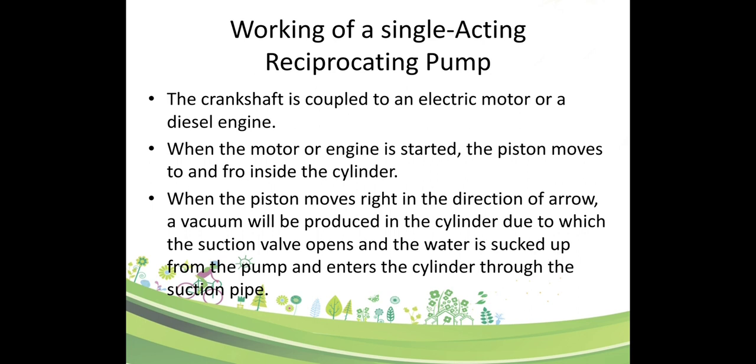Working principle of the single acting pump. We already said how to operate a single acting reciprocating pump. The crankshaft is coupled with an electric motor or diesel engine. When the motor or engine is started, the piston moves to and fro inside the cylinder. When the piston moves right in the direction of the arrow, a vacuum is produced in the cylinder